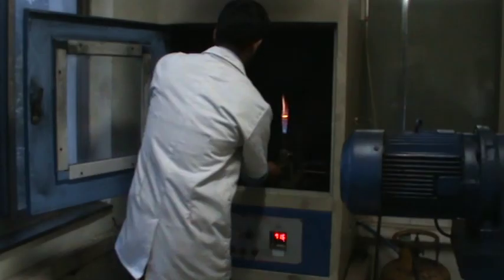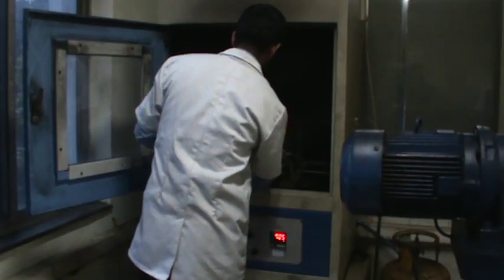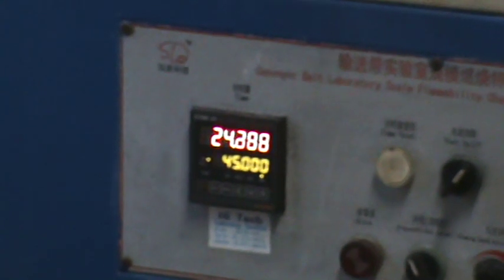E. Flame resistance. The ability of a conveyor belt to resist burning is tested using a flame testing apparatus, and it measures the amount of time in seconds that a sample piece of belt continues to burn after having been exposed to a standard flame. It also records the amount of time a belt sample continues to glow once the flame has been removed. The flame resistance requirement for belts used underground in coal mining applications is governed by Australian standard AS 4606.